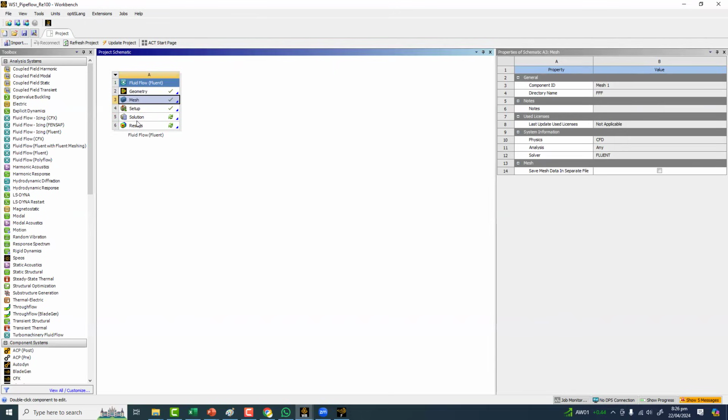But in the old times, because Fluent was purchased by ANSYS some time ago, Fluent can accept meshes from different meshing apps. So meshing apps don't know about the geometry units. They are unitless. If the geometry was made, for example, with a cylinder length of 10 meters, they will not take it as 10 meters, but rather 10 units, whatever the units are.